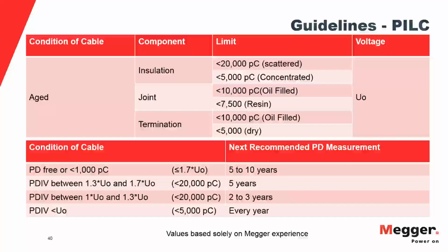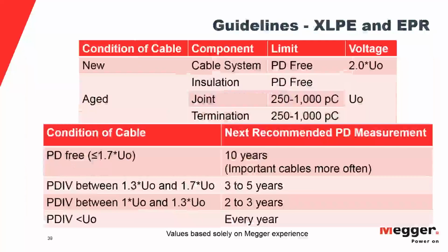And the square wave, the only real application that we have in the field is when you want to do a very quick proof test, like you used to do with the DC high pot, but you don't want to use the DC high pot. Then that's okay if you want to apply voltage for a very, very short amount of time. But as Jason correctly said, the sine wave is the internationally standardized waveform, as is the cosine rectangular, because that came first.